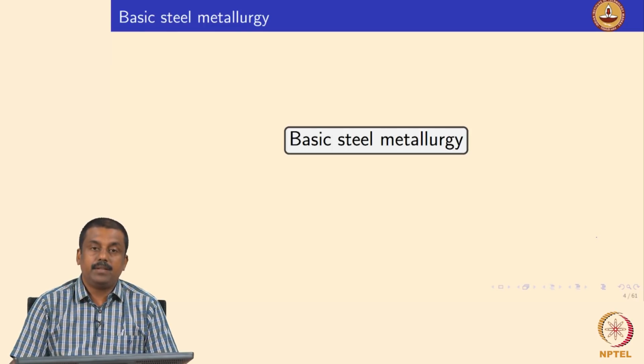Apart from these alloying elements, we also have impurities. Generally, phosphorus and sulfur are considered impurities. It's very difficult to remove them, so we have to work with them. Even if they are there in a trace amount, they may still cause various problems during welding.